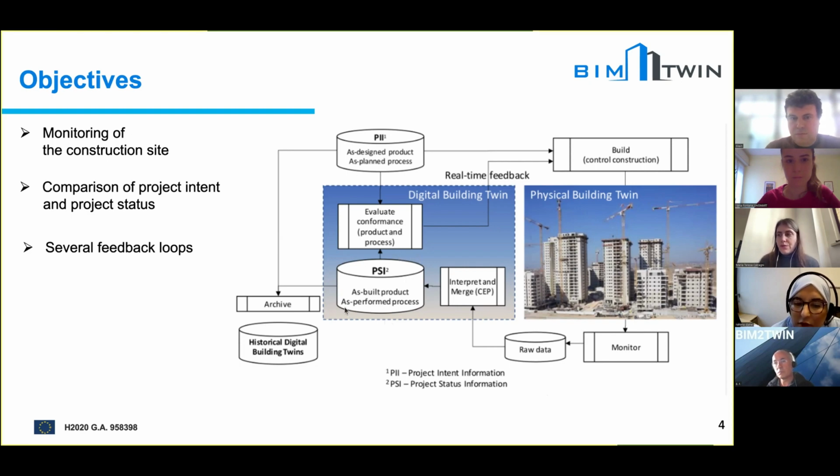This information will be sent after to the construction site manager. So we start from the construction site, we extract all the information we need, we make our comparison with the as-designed, as-planned information, we extract some significant information about the current progress and status of the construction, and we go back to the construction site.